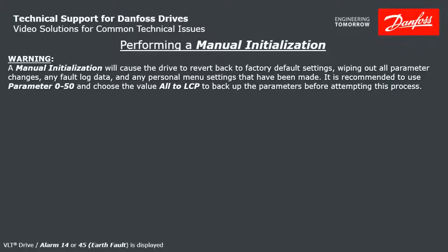Warning: a manual initialization will cause the drive to revert back to factory default settings, wiping out all parameter changes, any fault log data, and any personal menu settings that have been made. It is recommended to use parameter 0-50 and choose the value all to LCP to back up the parameters before attempting this process. Here are the steps to perform a manual initialization.